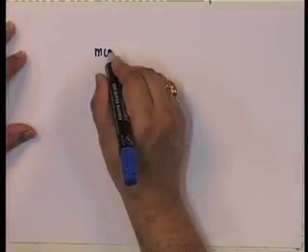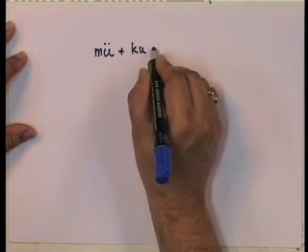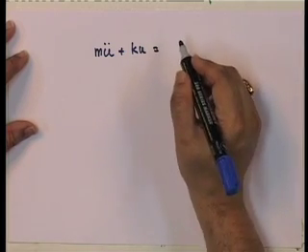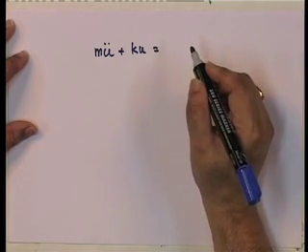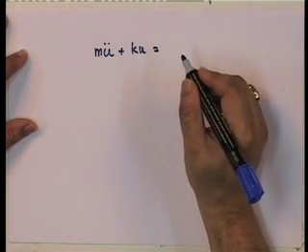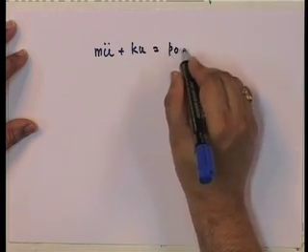So the problem is no longer the solution of m u double dot plus C u, but we can drop the C u term. Not because C u is 0, but because viscous damping takes time to happen and T d is not long enough for it to act.